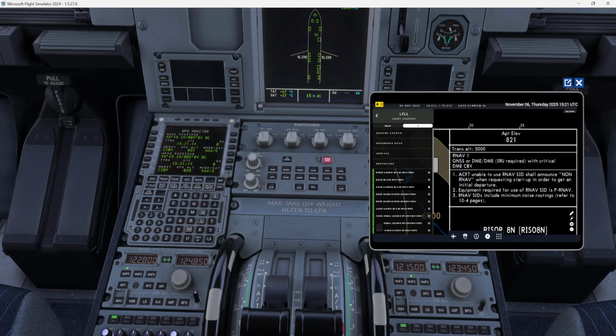Normally you should get 6, because why 6? Because in aviation they told us if you want to get the correction for errors and to detect the faulty satellites, you need 6. But if you want just to do the approach, you cannot get the faulty satellites. You need minimum 5. So in this case we need 5 satellites. This is also another subject we discuss later in detail.